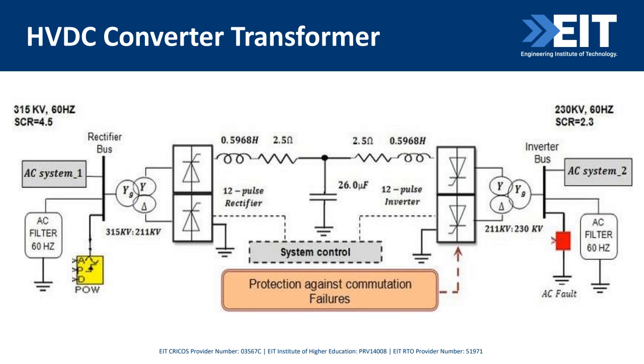And then we have this converter transformer connected to the valve bridge, and that will convert this AC to high voltage DC power. In some cases, we use a DC side filter as well, just to make sure that there are no DC ripples and harmonics in the outgoing power.